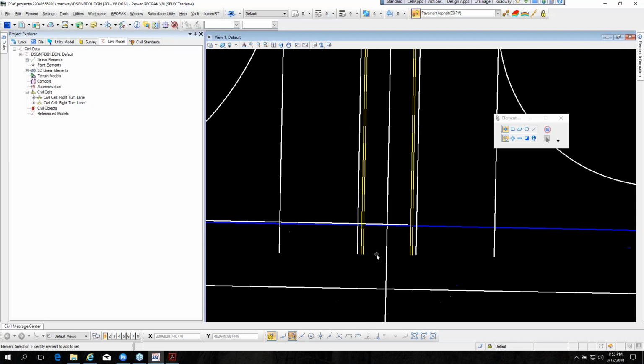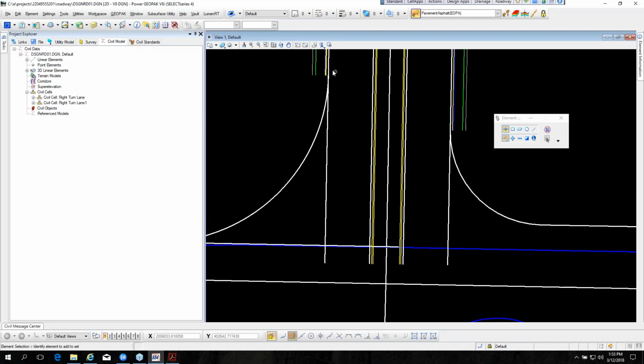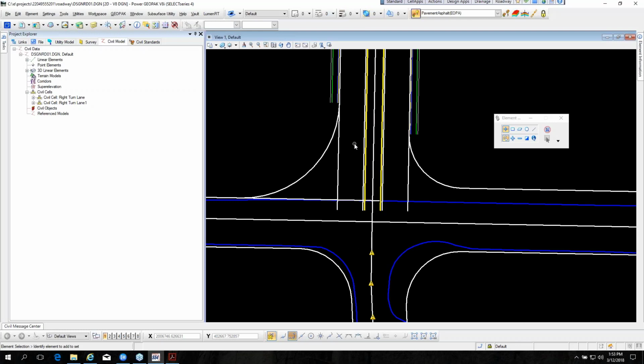So the first thing you've got to do is move it off this intersection where we snapped it, and then you should be able to manipulate these back to the curves that you want. And then we're doing what you said before, which is trim this. We want to leave this line in there for now because we have to put our median or our island in here, and it needs these 2 lines. But then we would trim this back to that point, or that line. I think that's what the exercise in 3.10 is doing.